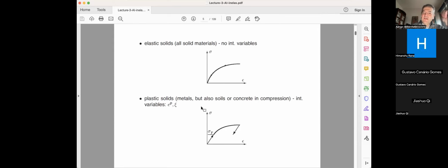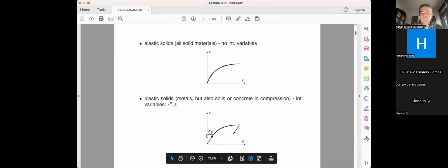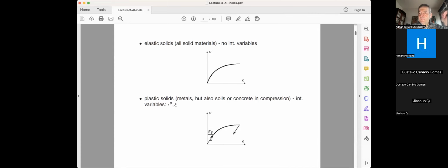Now, if you have plasticity, something like isotropic hardening, which might be non-linear, something like a saturation, basically you go linear, let's say for the simplest case, until the yield stress. This is the stress where the plasticity phenomena kick in. For materials like steel, a reasonable value is 400 megapascal and so on.